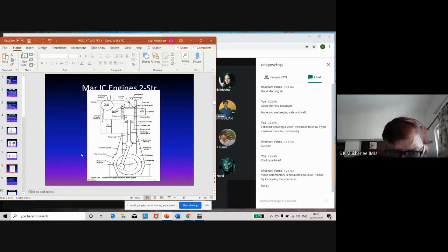For the crankcase, the lubricating oil is different. And sometimes for the turning gear, the lubricating oil may be different. So in one engine, you will have 3 or 4 different lubricating oils that are used. You cannot interchange one with the other. It will fail.